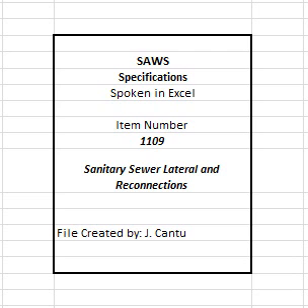D. Payment will be made for each lateral stub out or reconnection installed complete in place, including service connections, couplings, adapters, disconnecting existing services, reconnecting new service, fittings, excavation, backfill, and testing as required by specification item number 804, excavation, trenching, and backfill. E. Payment for sanitary sewer laterals more than 10 feet laterally from the sewer main shall be governed by specification item number 854, sanitary sewer laterals.